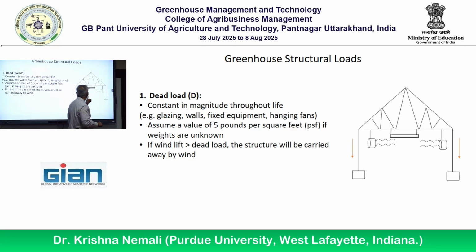We want you to keep that number in mind. Assume a value of 5 pounds per square feet, or you can convert pounds to kilograms and square feet to meter square. That is what the units you get. But at a minimum, it should be that's what we're recommending. Okay, 5 pounds. This is a very important thing. This is where companies make a lot of money, by giving you some cheap material, and you look, it's a wonderful greenhouse, 3-4 months later it's blown away, it's gone. But that load also includes, in case you're putting some fans, everything is included in that.